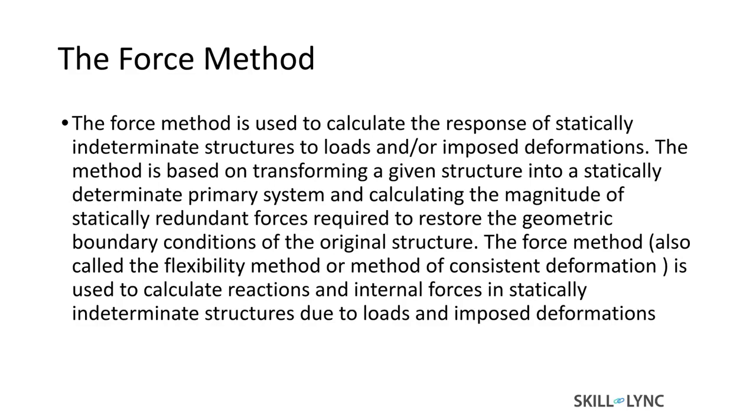So it basically expresses the relationship between displacement and force that exists in a structure. The primary objective of the force method is to determine the chosen set of unknown forces, the redundants. Like you can think of unknown forces to arrive at known displacements. The number of redundants is equivalent to the static indeterminacy of the structure. So that's where the degrees of freedom come into place.